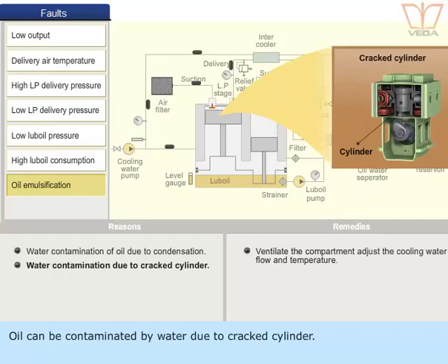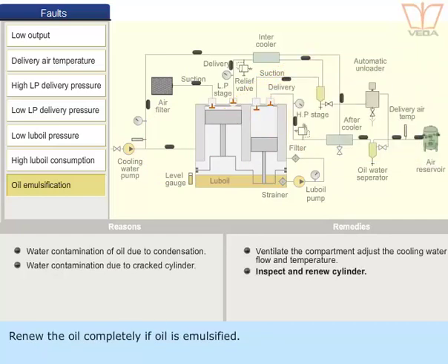Oil can be contaminated by water due to a cracked cylinder. Renew the oil completely if the oil is emulsified.